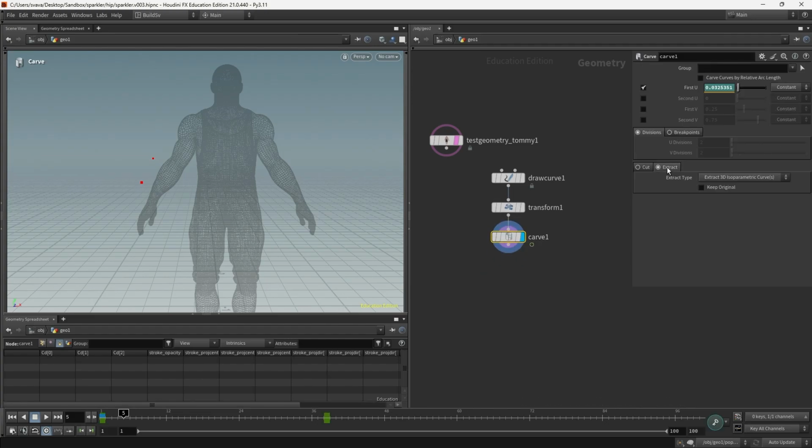But I think I want to use the cut option rather than the extract option, because I want to kind of use this line as motion blur. And then I'm going to move both keyframes a bit forward, so I'm going to hold shift and select the parts I want to keep. And then I can let go of shift and just middle mouse click anywhere in the selected area, and then you're able to slide it around like this.